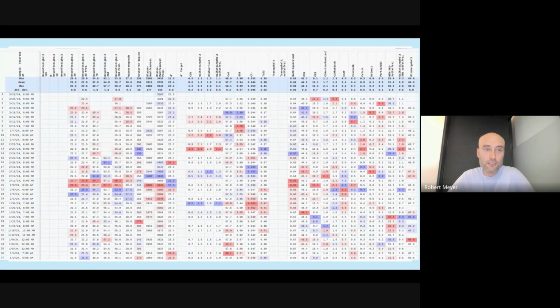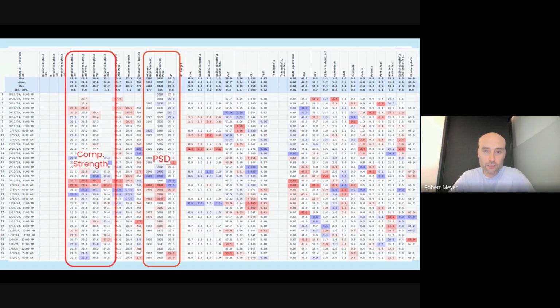And this is how this data looks like in reality. So basically, you can think of it as a giant Excel sheet of all their laboratory data. There is our target, so the real compressive strength tests that are still being made. That's the one that takes usually 28 days, because you have to form this concrete cube, let it sit and harden for 28 days, and then crush it. And then we have our input data. So for example, this reflects the particle size distribution.